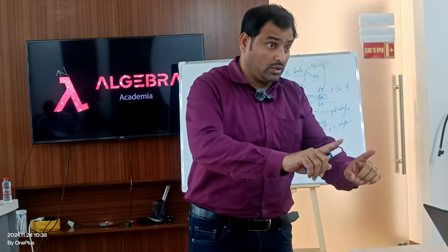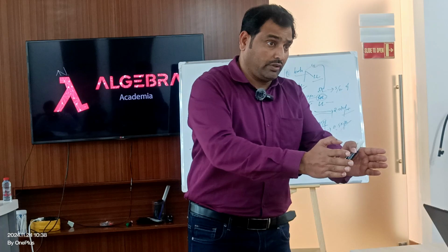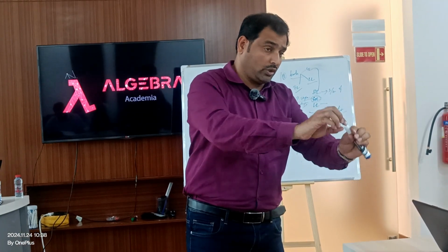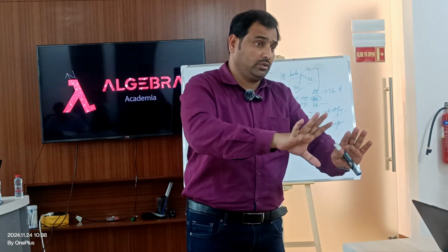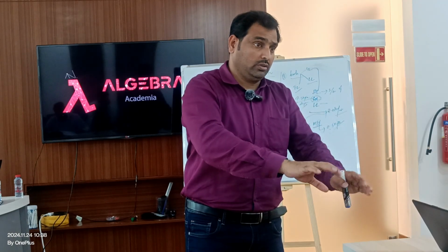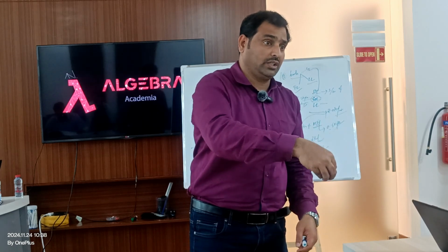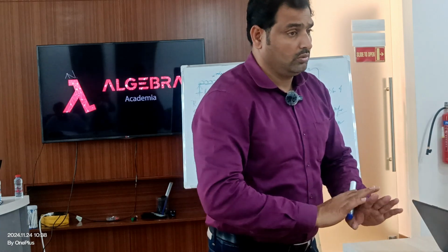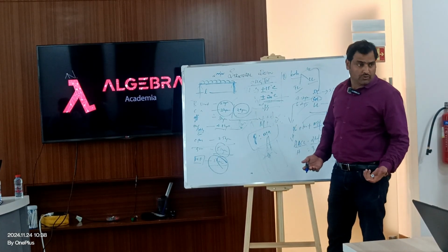That is what the authority argument is. But the code argument is, if it is less than 45 meters, you don't need to consider the temperature. If it is more than that, you can consider it. The authority argument is, when we had a debate, this is what they said: if it is stopped, then definitely this slab is going to be expanded. And where exactly are you having the counter reinforcement? There is a constraint. If you multiply by the area, then you will get the force, isn't it?